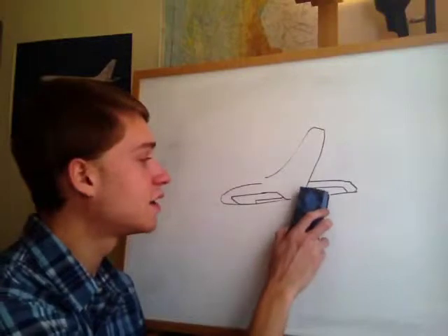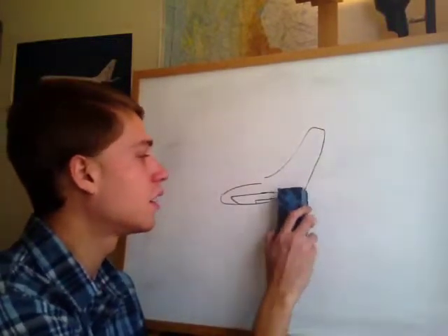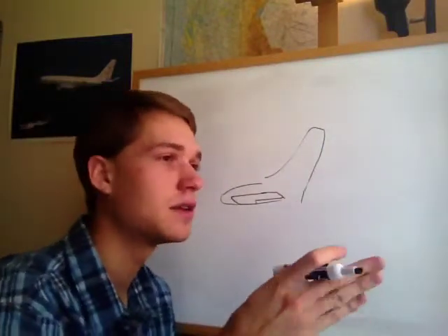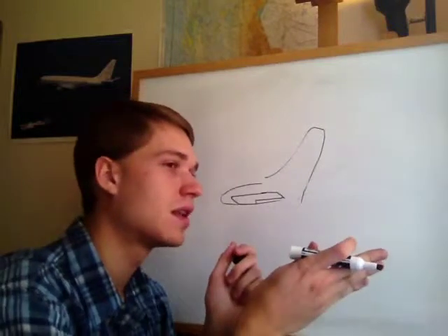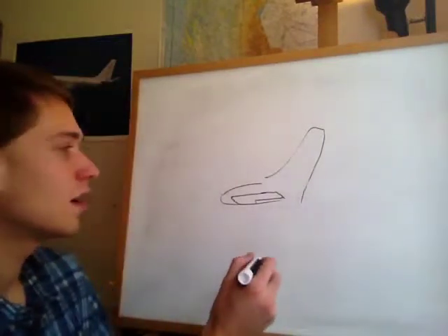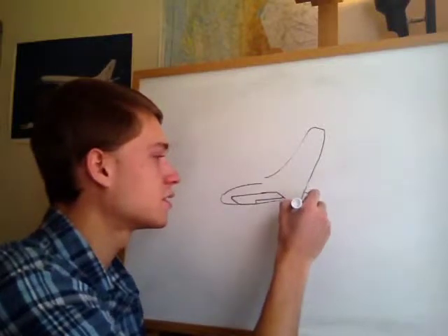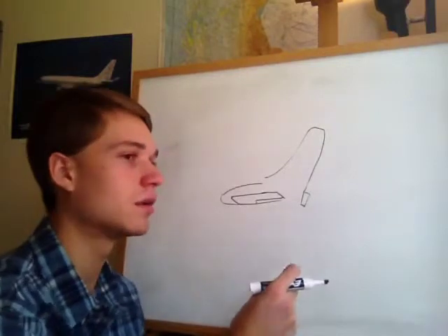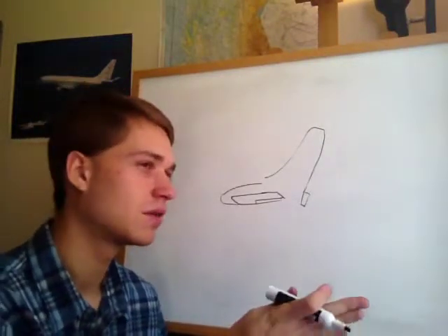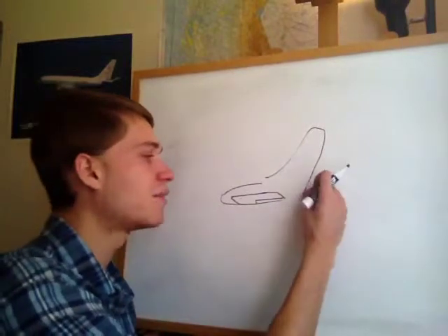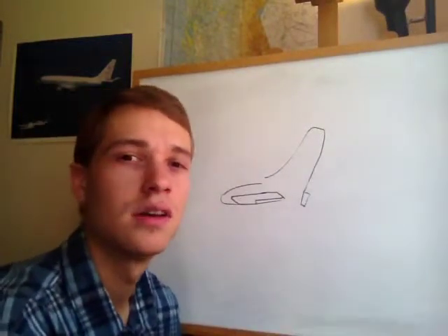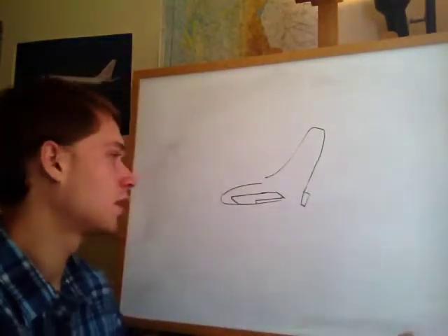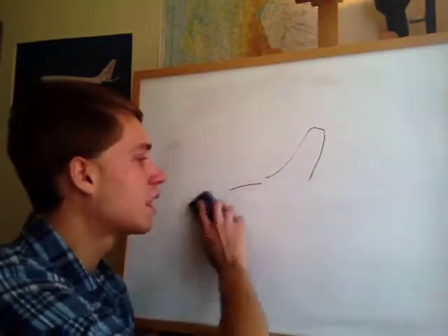What they might have is something called a manual trim tab for the rudder. If you're flying along and you notice that the airplane tends to yaw off to one side, then you have this little tab that you have to set manually on the ground, and it's just trial and error. You come back from a flight and say, okay, the airplane was yawing a little bit to the left, so I'm just going to bend this thing to the right. You'll see this on a lot of training airplanes, this little bendable trim tab on the back of the vertical stabilizer.